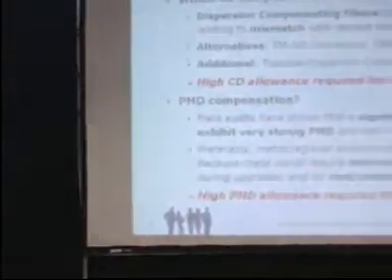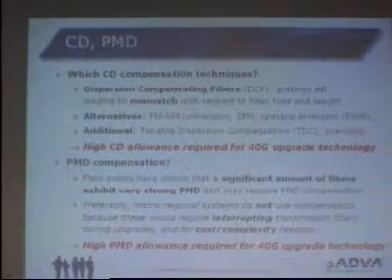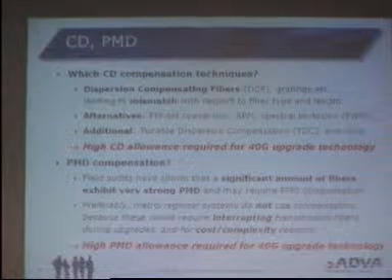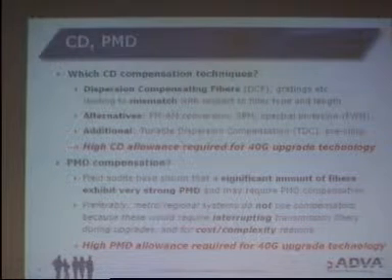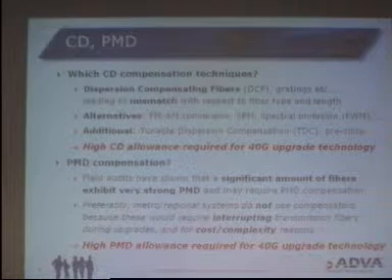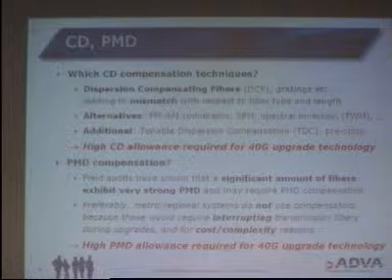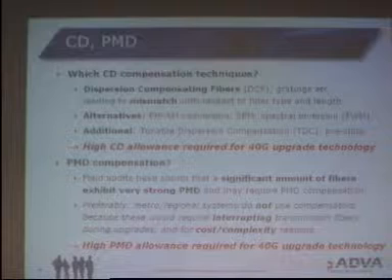Normally we do so by using dispersion compensating fibers. There are other alternatives, like the use of spectral inversion, which was the topic of the first talk. So if I mirror a wavelength into another dispersion domain of the fiber, I could cancel the total dispersion. Theoretically, it's possible, and maybe it can be used. But typically, it's more used by using fibers with plus-minus signs of the dispersion.